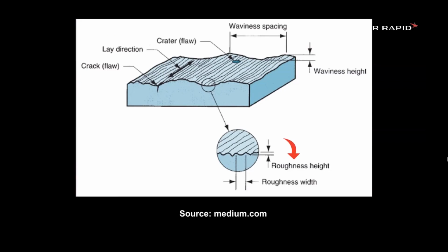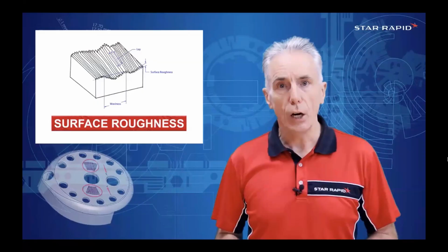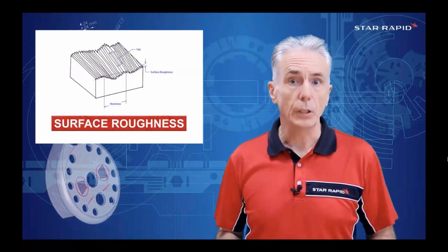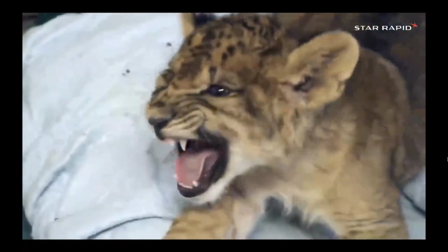As mentioned, rough. And so this line will fluctuate over a given distance. Roughness spacing is the grooves or their frequency. The lay is the dominant direction of the grooves. And then there's waviness, which is more like a periodic repeating distortion over a longer sampling length. So a low Ra value means little deviation or a very flat or smooth surface, while higher numbers are rougher.